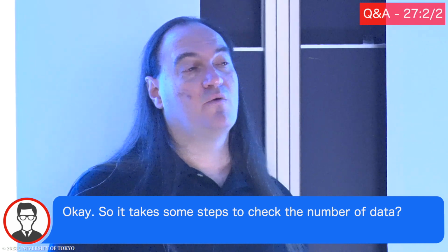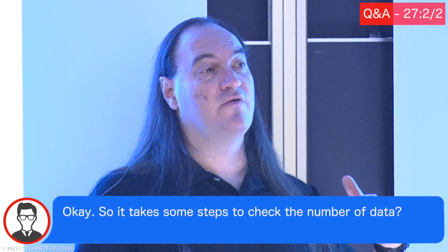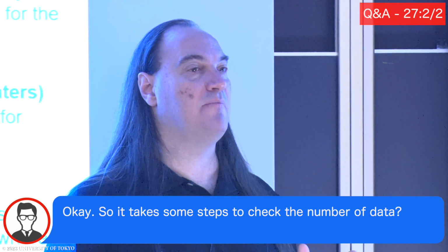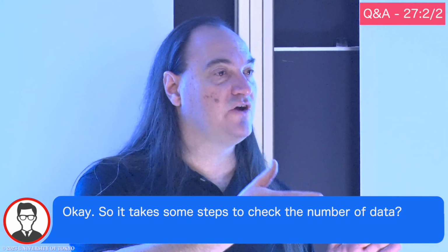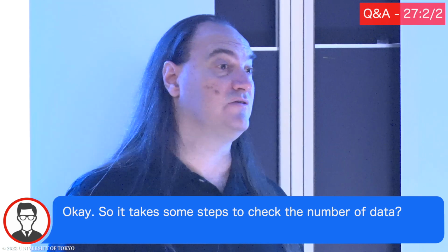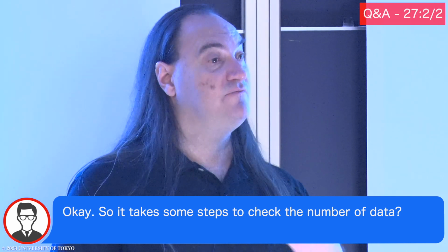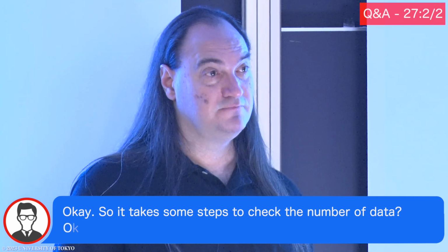Yes, if you don't wish to look through the output file. The output file does tell you the number of loops when you go there, but you're only doing that every output iterations. So I might solve every 30 seconds, but output every 300. I don't know how many loops it's taking at each of those 30 seconds. I only know how many loops it took for the time that I output at 300 seconds. So if you wish to know more frequently than the output interval, then you need to write your own logic. If you want to look at just the output interval times, you could get the information there.